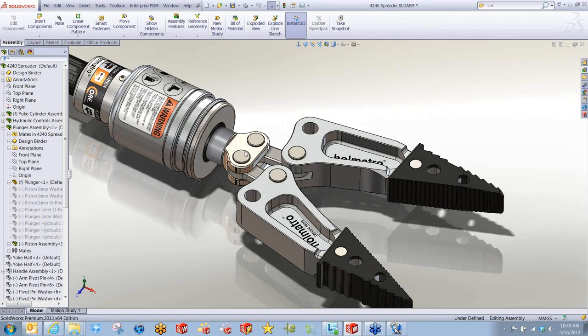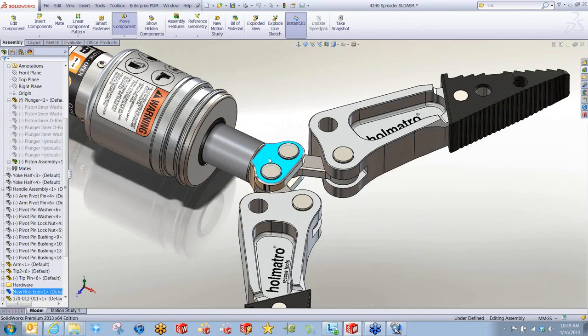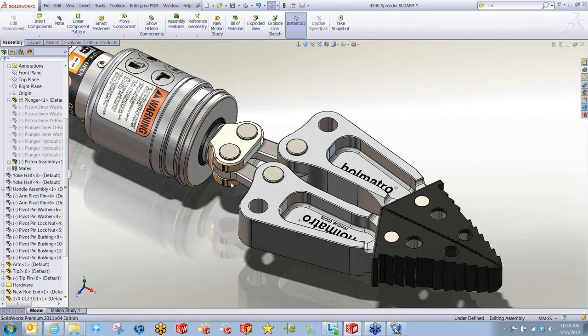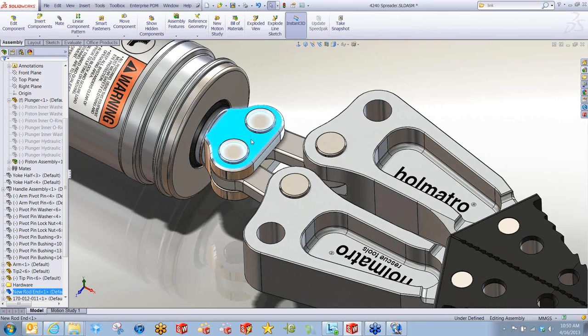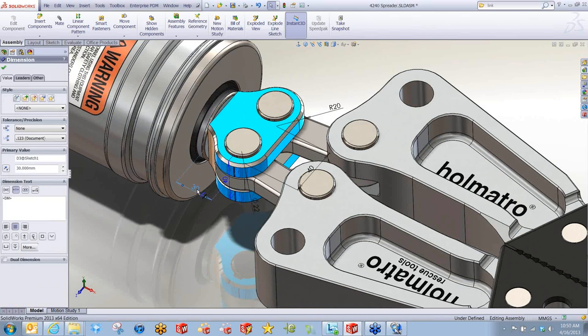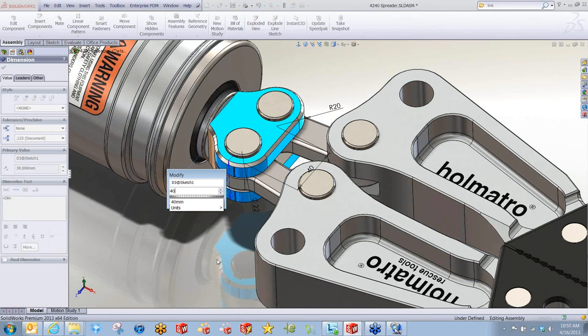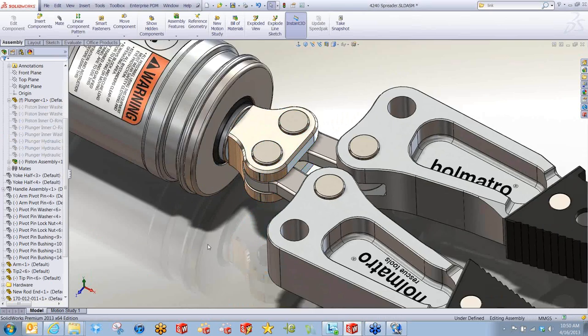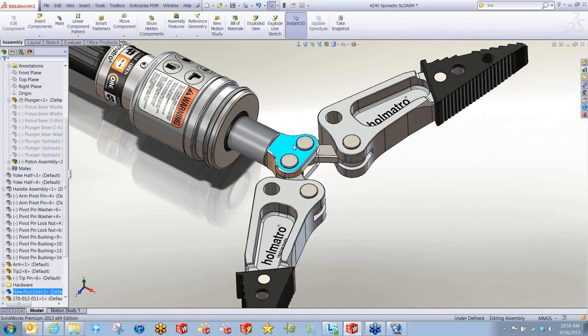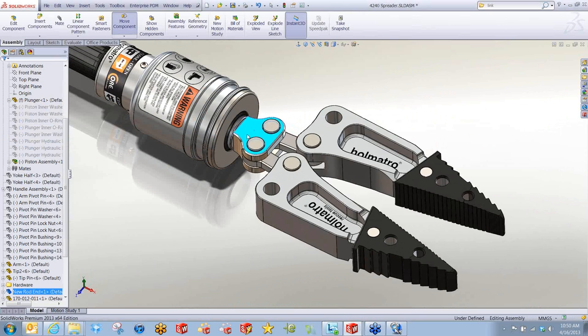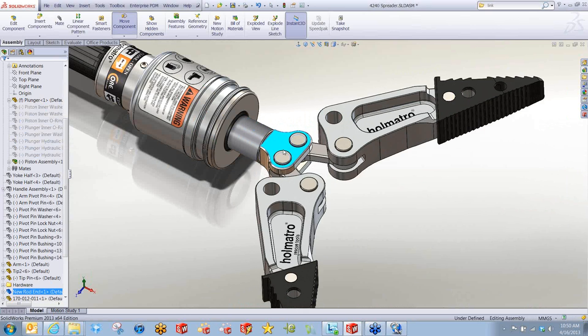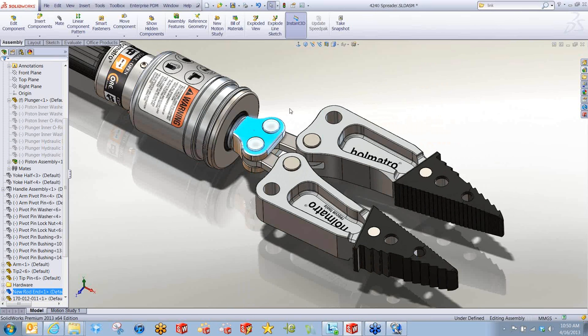All right. Okay, now we've got our full range of motion in here, and notice my arms are coming together perfectly. Well, that's because I knew what dimensions I wanted, but let's test out what would happen if we still had an incorrect size in here. And notice now I'm putting my assembly through the full range of motion, and the arms aren't quite coming together. So that's a very easy design mistake to make, and if we didn't catch that in time, that could be really costly.